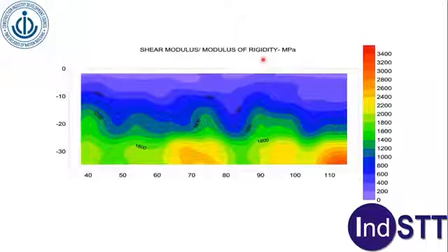Here the emphasis is to give a quality level to each utility which is put on a map. That is, once you look at the map, you know how much you can trust that map. That is the basis of the entire SUE operation. There is quality level D, C, B, A, where obviously quality level D is the least reliable information and A is the highest, the most reliable information.